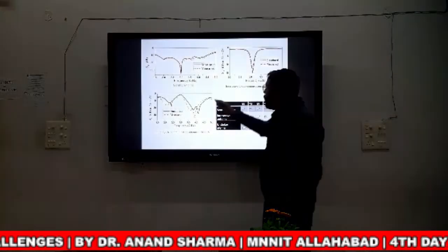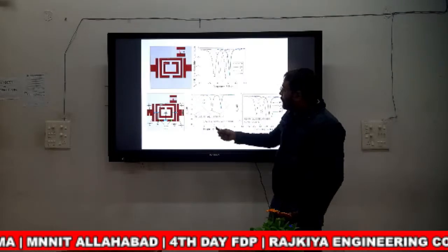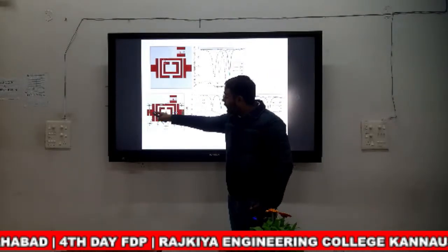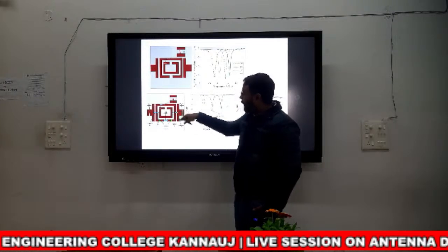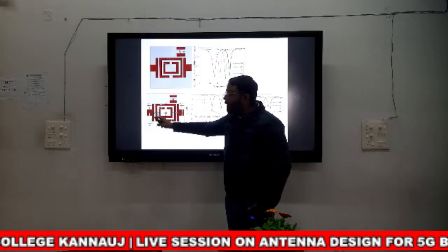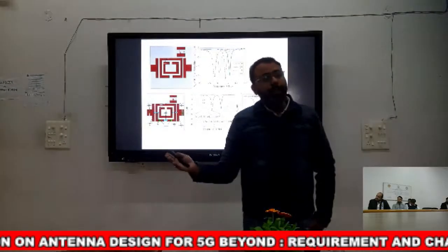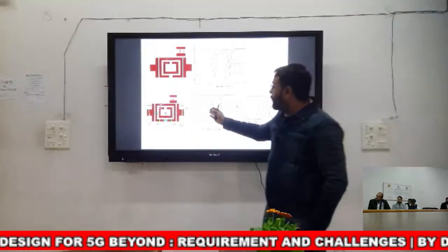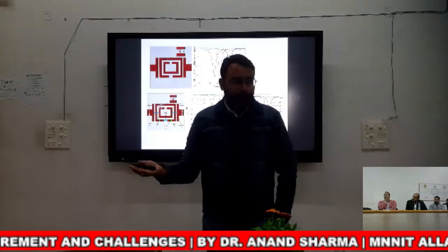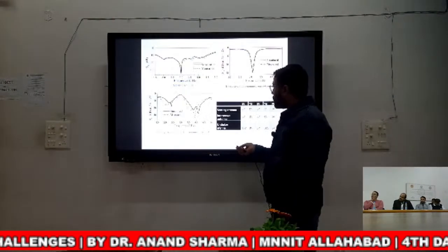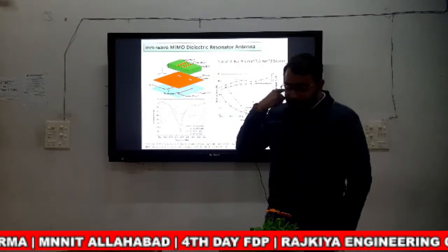By changing the reverse bias voltage of this varactor diode and by on and off of the pin diode, we can create three different types of characteristics known as band pass, all pass and band notch. And by creating these characteristics, you can design an antenna for a CR system, which is more smart cognitively. It is used for efficient utilization of the spectrum.